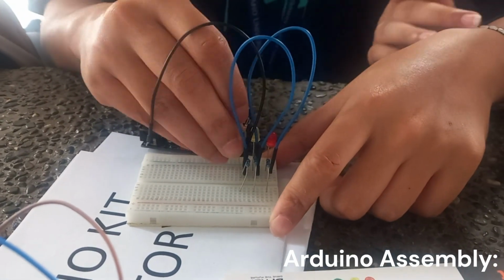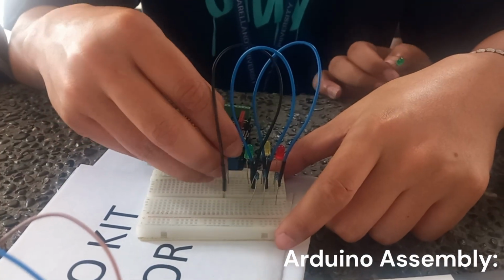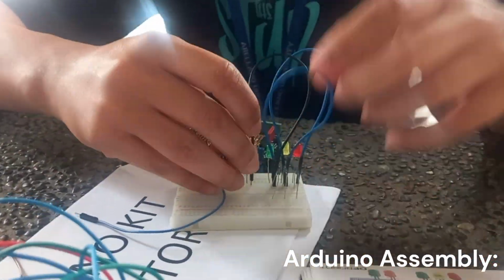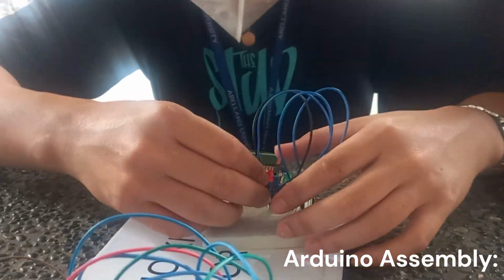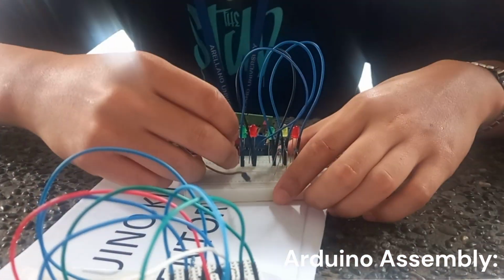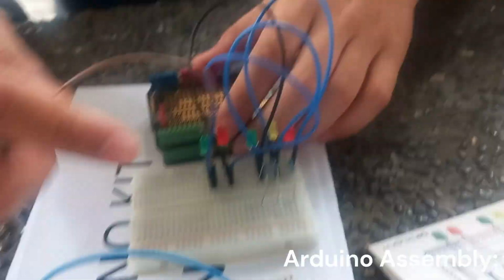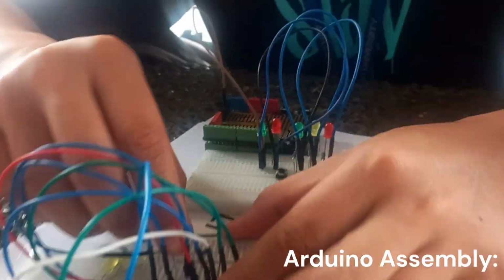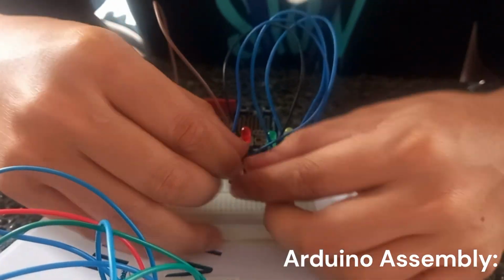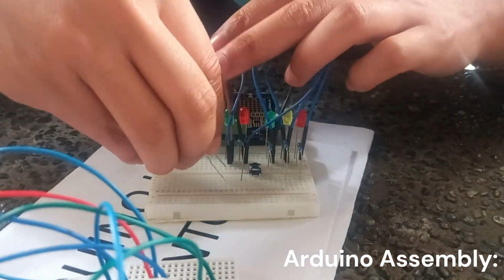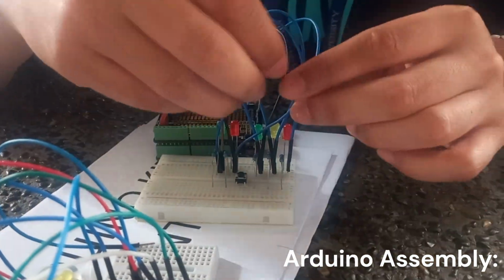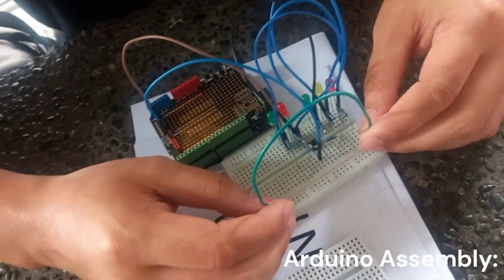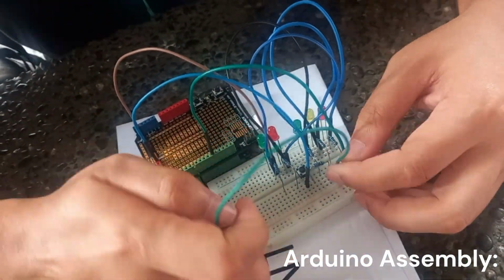Connect the LED and the other resistors according to the wiring diagram, as well as the jumper cables male-to-male for the vehicle and pedestrian lights to their respective digital pins. Then, connect the push button that will serve as the input of the circuit. After that, connect the three remaining resistors and the other jumper cables male-to-male. After connecting the components to the breadboard, connect the Arduino controller and the computer with the provided USB cable.